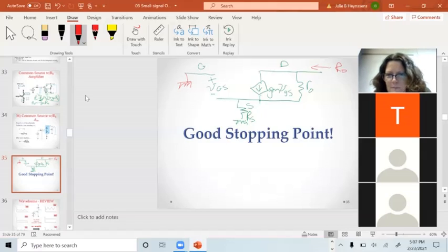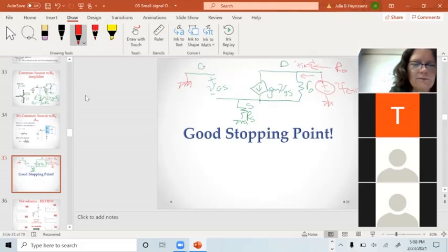Now I still have that dependent source in there. So the quickest way I know how to do this is I put a voltage here, and I'm going to call it V test. I want to find that resistance. What I need to figure out is what I test is. In my Thevenin equivalent, V equals IR, R out is going to equal the ratio of V test over I test.